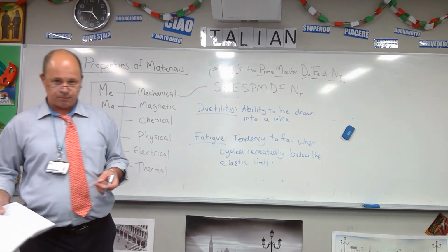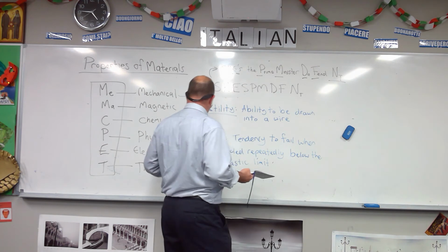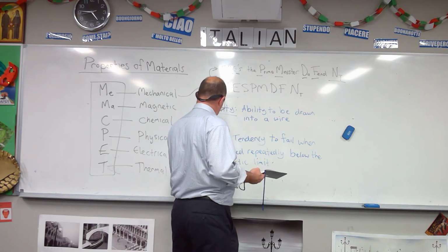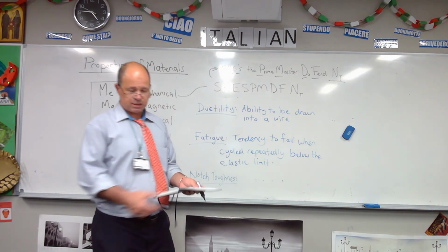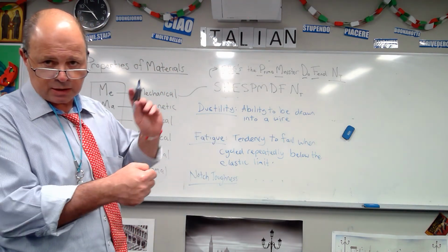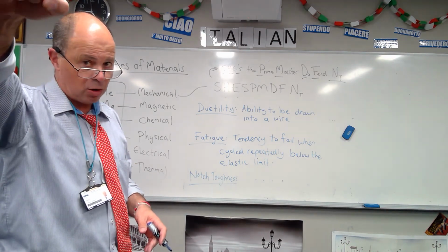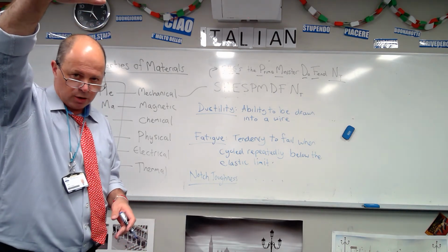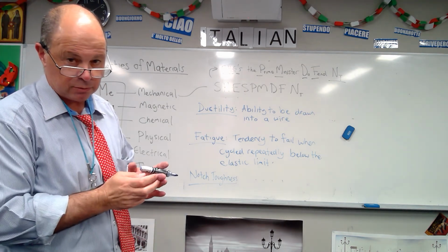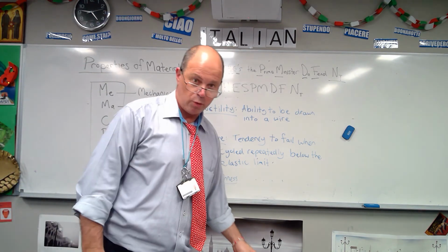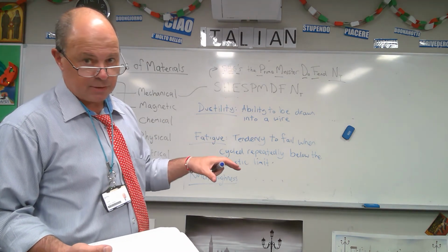So that's our fatigue. So we've got one last one, which is the N small subscript T, and that is notch toughness. Now you can test a material to see how well it can receive a shock load, because some materials you can put weight on gently and keep loading it up and loading up and take a whole lot of weight. But if you drop the weight on and shock it, it will fail. Okay, especially materials that are brittle quite often will fail well below the load that they can actually hold if the loads are being applied statically rather than dynamically.